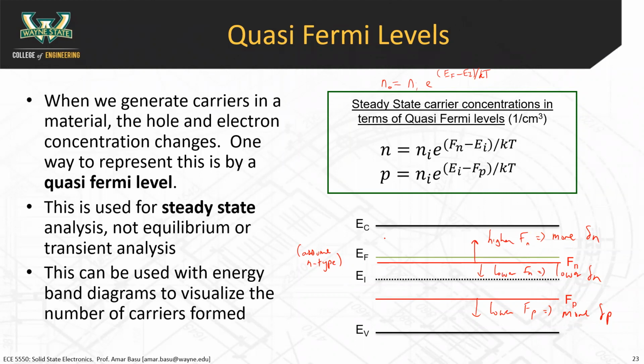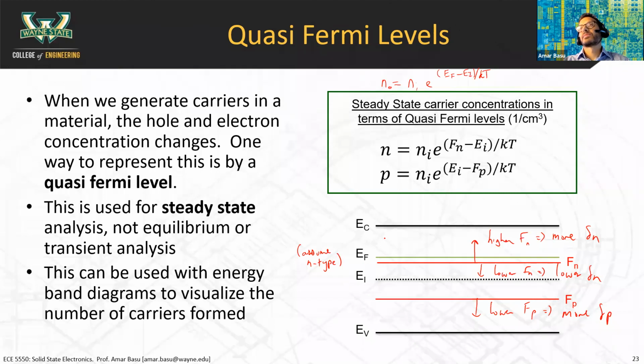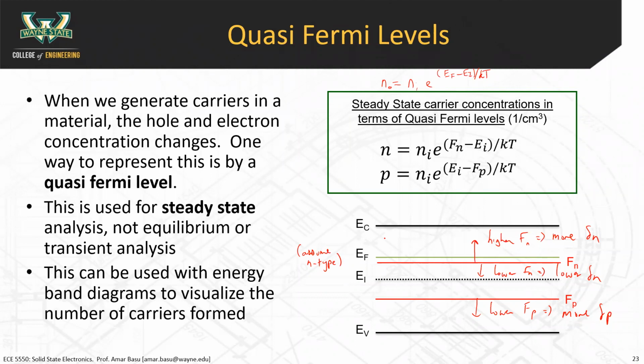There's a probability of more electrons towards a conduction band. Exactly. So what type of semiconductor is it? That would be an N-type. N-type, right. And what happens if we dope? Well, what happens to the Fermi level if our electron concentration goes up? If we dope the material more N-type, what happens to the Fermi level? It shifts upwards. It shifts upwards towards E sub C.